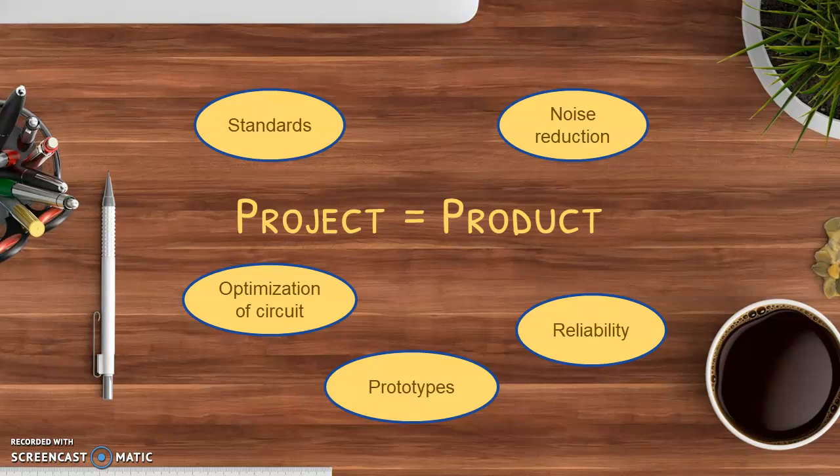Reliability is very important. So what if I have a circuit which works perfectly when I'm trying to work with it in my laboratory? What if I carry the same circuit to somebody else's laboratory and it doesn't work there? Or what happens when there is a rainy season, there is moisture and there is dust all around? Will your circuit work, yes or no? If something fails in the circuit, will the entire thing stop working, or is there something else that you have provided? So that also we need to check.